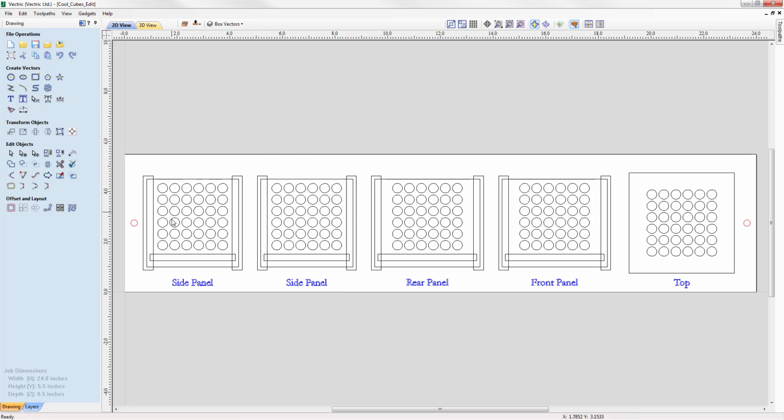We're going to look at taking all of the decorative elements of the box along with the profile cutouts, and we're going to move them to the other side. Okay, so to do that, we're just going to select the vectors by dragging a box up to the top left location, and anything that touches this selection box will be selected.